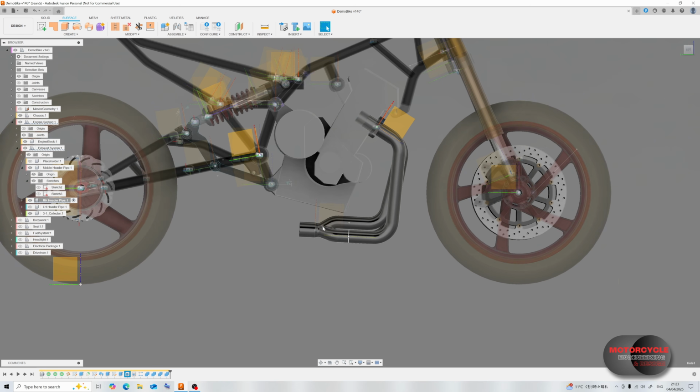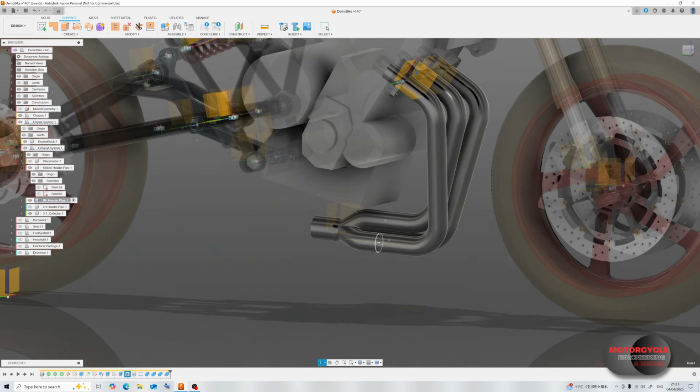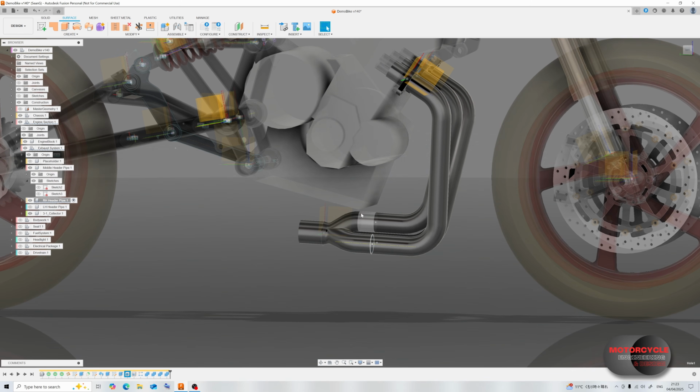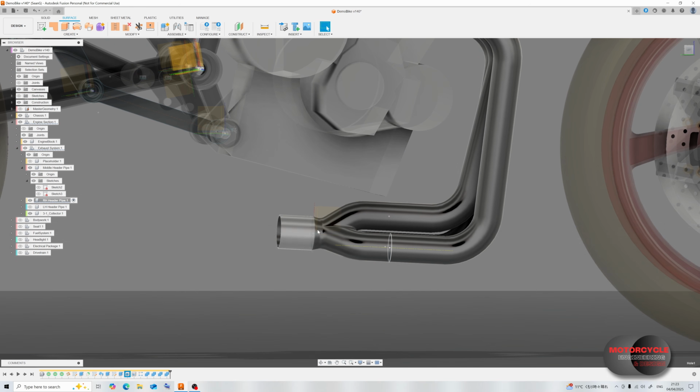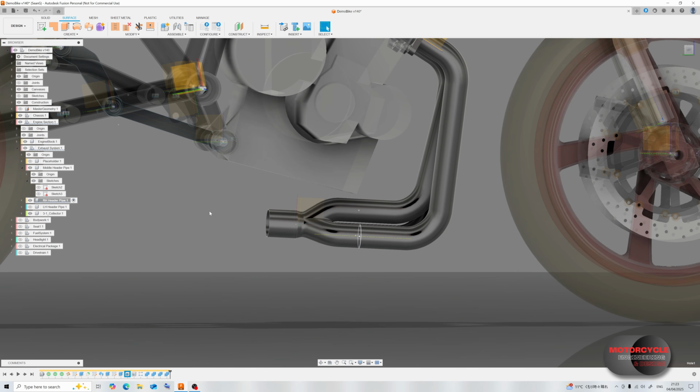So for a production motorcycle, obviously they have to worry about regulations and emissions. So from this collector, we'd usually go directly, or maybe not so directly, but we will go into a catalytic converter. Within that, you've essentially got a lattice shaped construction. All of the surface area on that material, once it gets hot, it's able to absorb and catch the emissions that we're trying to prevent being exhausted to the atmosphere.